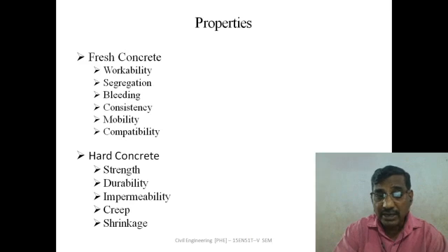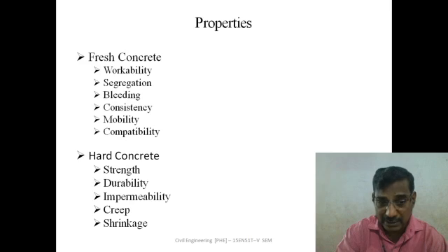Properties of hard concrete: strength, durability, impermeability, creep and shrinkage. Generally, the strength of the concrete will go on increasing with age. If the mix design is correct, if the curing is correct, if the workmanship is correct, then the strength will go on increasing.